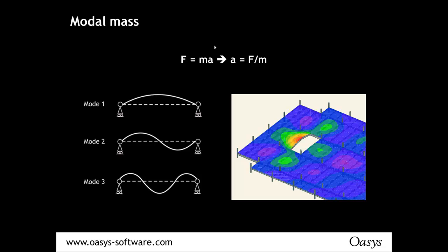These tend to have quite a low modal mass, and so these isolated bays are the ones where you actually get the worst response values. You do see a certain amount of nonsense from some vendors out there who say that isolated bays are not a problem. That's basically because their software can't calculate those areas, because they're just dealing with the simplified methods from the codes, which just can't cope with complex situations like this.